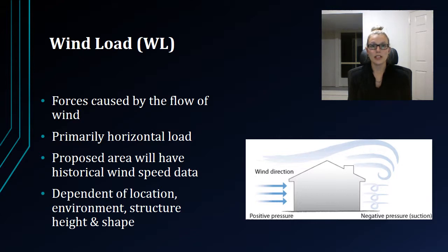Wind loads have the potential to cause tall structures to sway. In these cases, cross-bracing is used for extra stability. Cladding must also be secured to the structure, along with the dead load being heavy enough to hold the extra weight of the cladding and resist wind loads imposed on the structure.